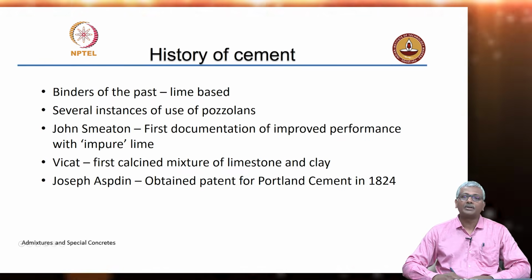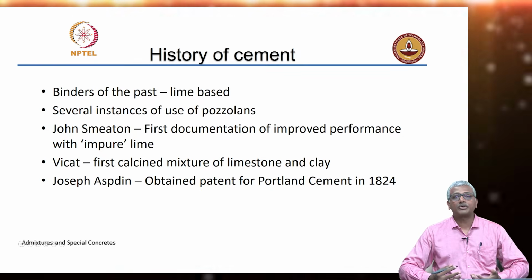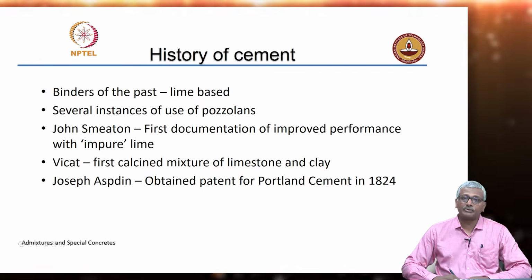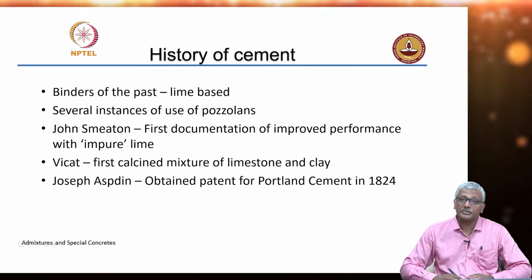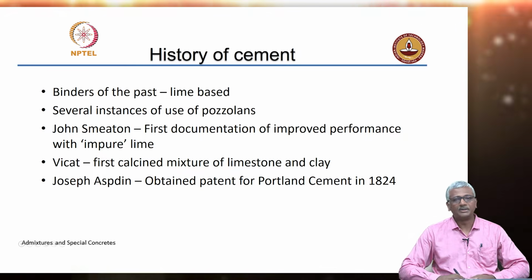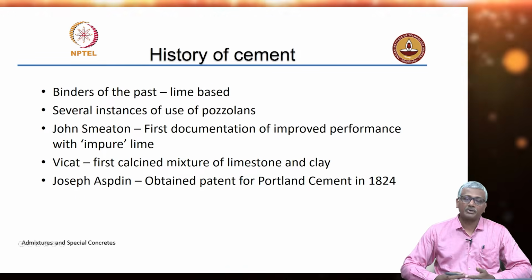In India, for instance, if you go to the southern part of India, a lot of the heritage monuments seem to have lime mortar, in which they have actually looked at an extract of natural materials such as jaggery and kadukkai. Similarly, if you go up to the north, you will find that a lot of dals, pulses have been ground to a very fine powder and used with the lime mortar, just to give it the right consistency and sometimes to give it much better properties.